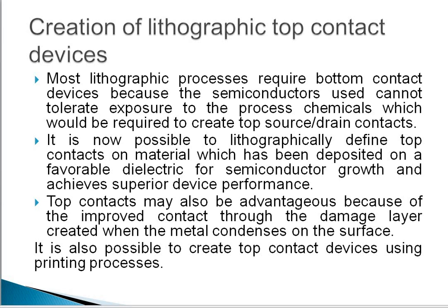Top contacts may also be advantageous because of the improved contact through the damage layer created when the metal condenses on the surface. It is also possible to create top contact devices using printing processes.